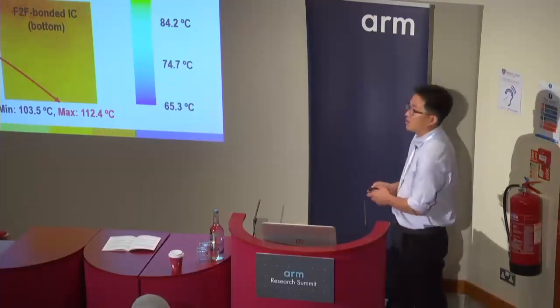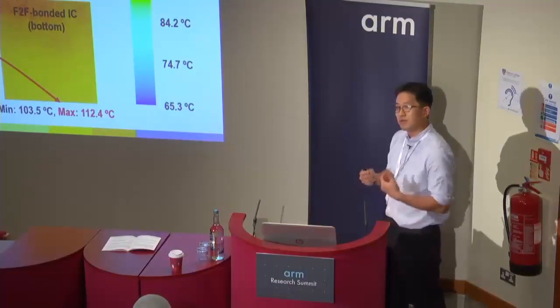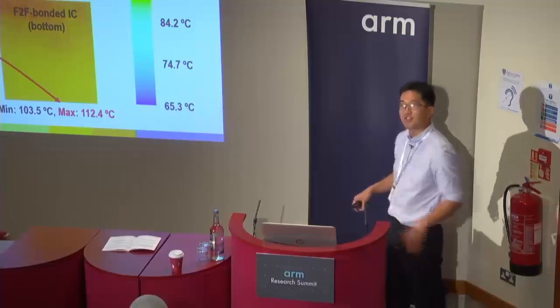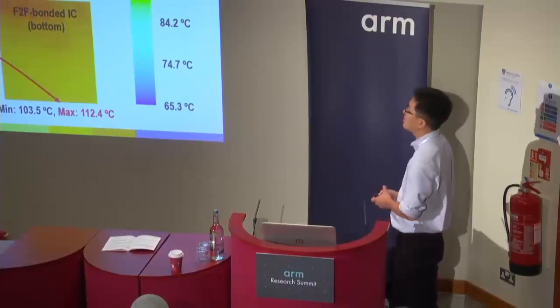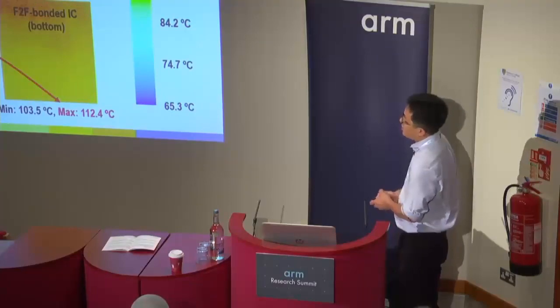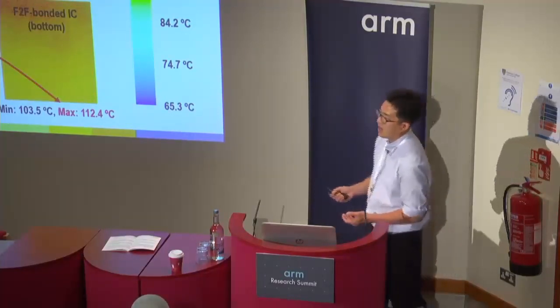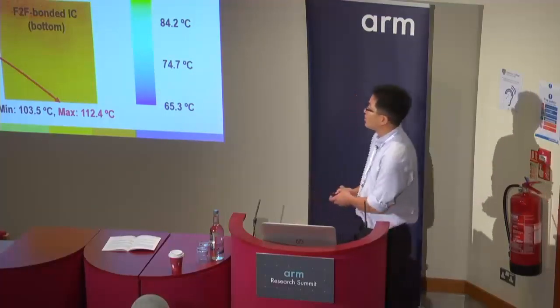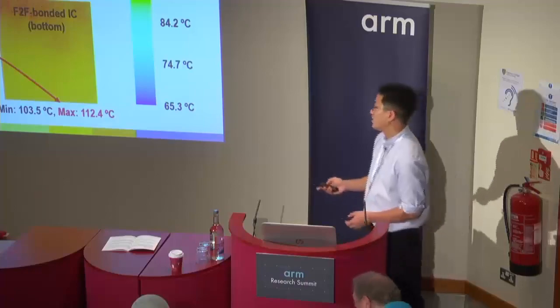But in the bottom tier, heat has to go through the PCB layer, which is a good channel, but it is less efficient than the heat sink. Also, there is a 40-degree higher temperature compared to the 2D design active layer than the F2F bonded 3D ICs.